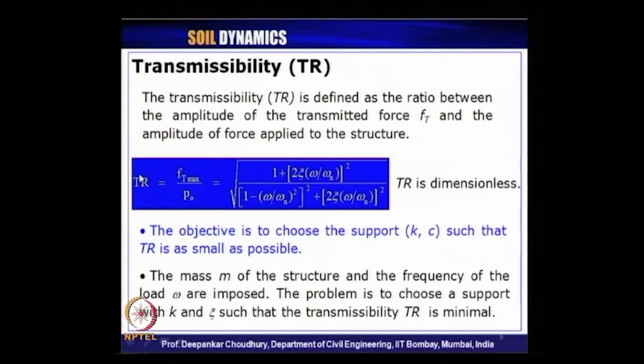Because small transmissibility ratio means that, for the given force to the system, on which hardly you have any control as a civil engineer, since that is provided by the machine manufacturer or supplier, you can design the system in such a way that the force transmitted to the base of the foundation should be minimum, right.